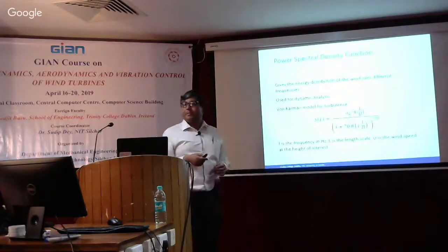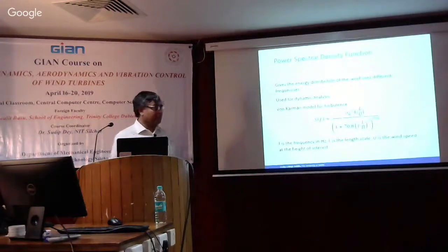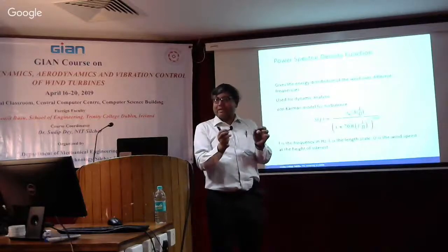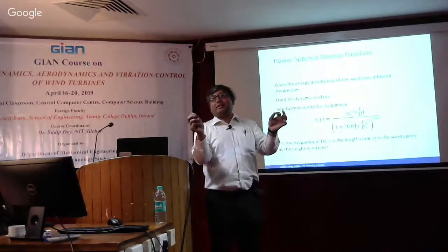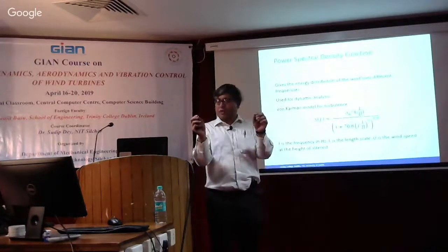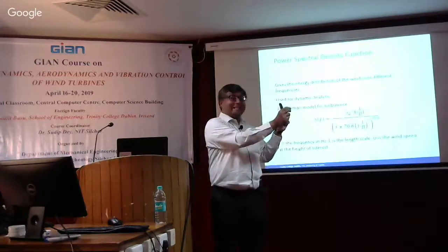And question: you drew the eddy current, is it around the cross section of the wind, or is it like a separate current evaluation? Yeah. So this is in a 2D framework I've drawn. So it's essentially planar. All I'm saying is that if you have two particles within the same eddy, they will be correlated. If they're outside, then there is no correlation. Therefore, the point corresponding to the zero autocorrelation in time is actually equivalent to the length scale of the eddy.